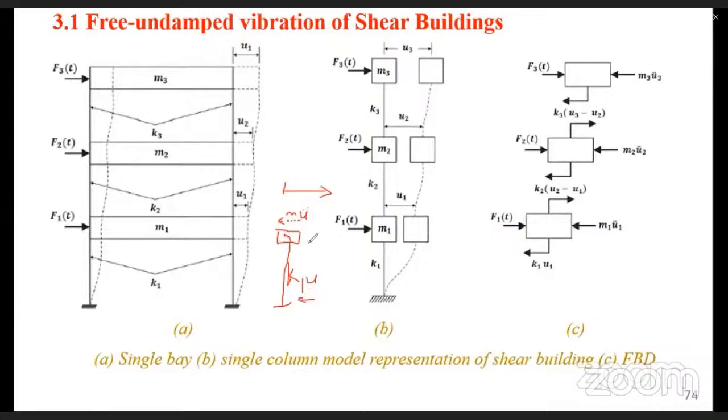And if there was damping in our system, of course, it would be trying to stop our motion. So in essence, for a single degree of freedom case, this part on top will not be there. The free body diagram will only have the externally applied force, the restoring force due to D'Alembert's principle, and the restoring force due to the stiffness. And of course, if there is damping, the c times u dot would again act in the direction of the restoring forces.